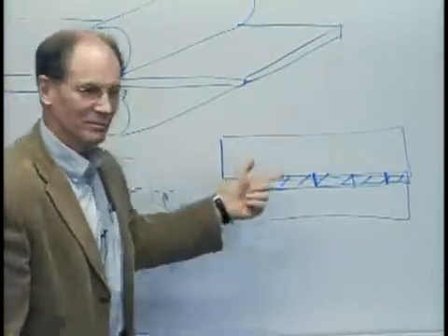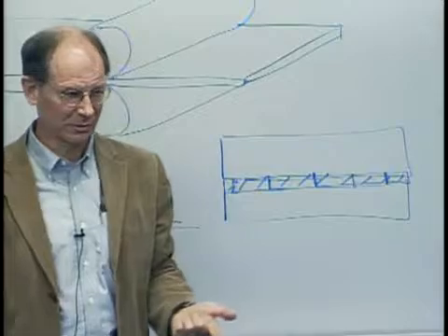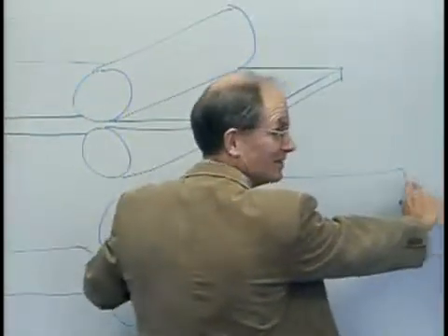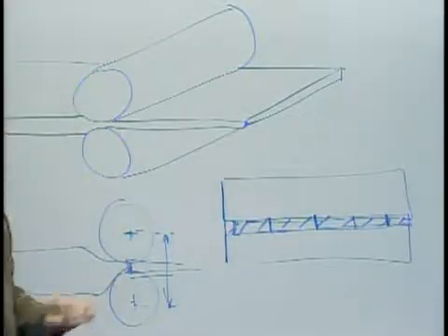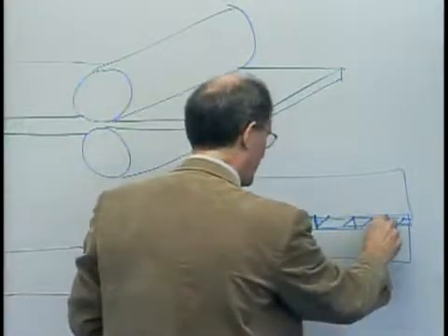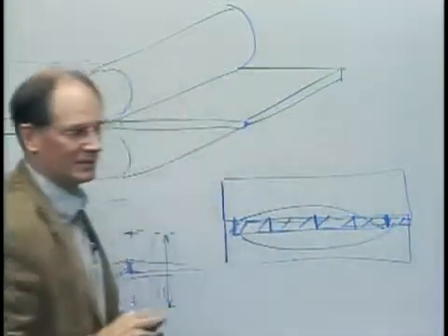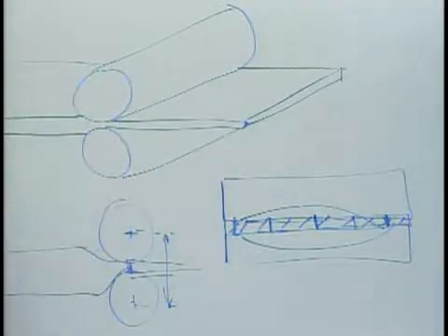Well, I'd actually probably have to change the shape of the rolls, right? You can do a little bit. They actually do both sides, and that does help. But let's say I do both sides, so this is exactly right, this is exactly right, and the middle looks like this, which is not uncommon. It becomes fatter in the middle. What do you do?